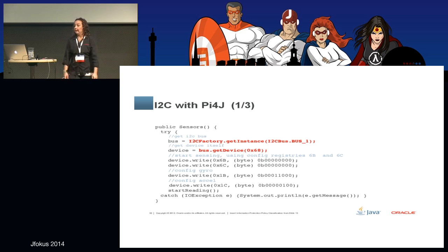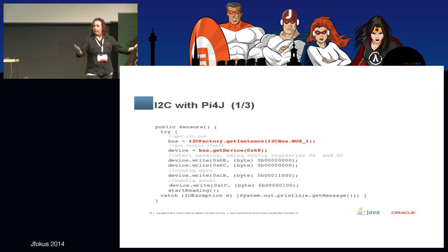How clever is that? If you don't do the next 2 lines, that is writing zeros in these particular 2 registers, you get no reading. It took me a couple of days, seriously, to find out that I need those 2 lines to be able to run my code. So most of the time, you spend the time on something totally useless to get your project working. Anyway, again, this is particular to this device. Other devices, so for the hands-on lab, I was using a different device. It was a biometric sensor. So I'm like, oh, but I already did I2C. Come on, I already know everything about it.